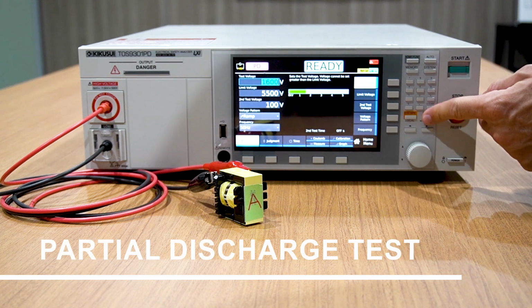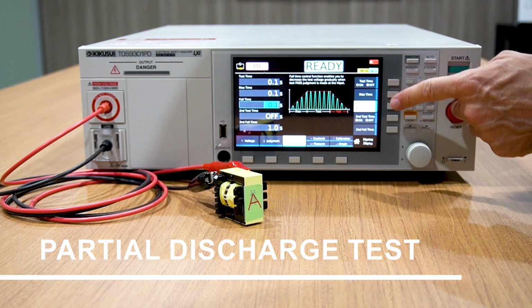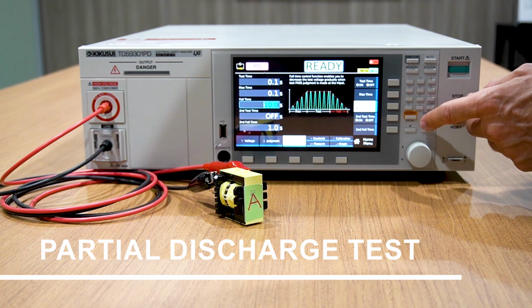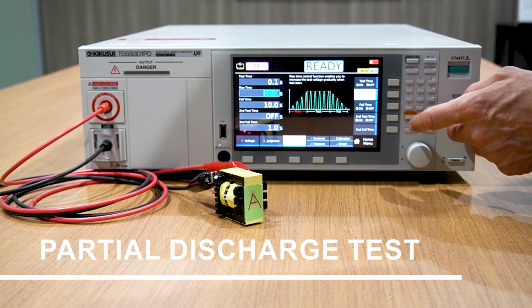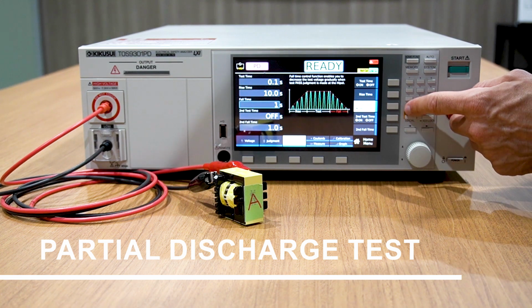After connecting the wires to the primary and secondary sides of the transformer, we'll set up the TOS 9301 PD. We'll set the test voltage to 1600 volts. The rise time, fall time, and test duration will all be set to 10 seconds each.